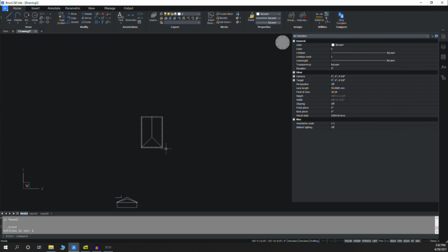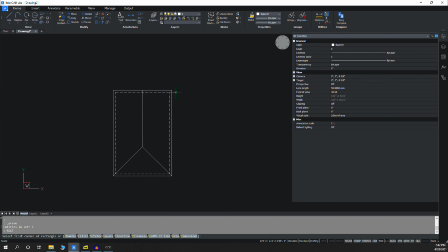With a hip roof, you might want to look at what this looks like from the other elevation. So in that case, we'll just draw another side elevation here, and I'll catch this line here, and I'll catch that line there. And remember, our building was 10 feet tall, and so now this is an elevation, but it's kind of sideways on us. In AutoCAD, you actually can flip the view.